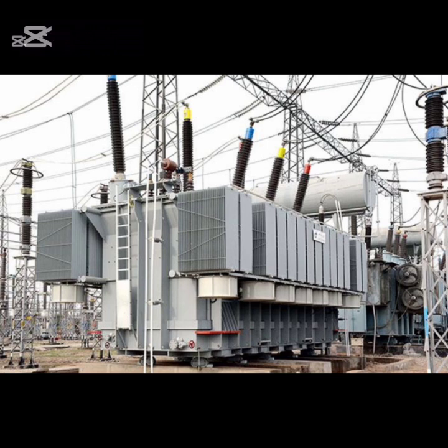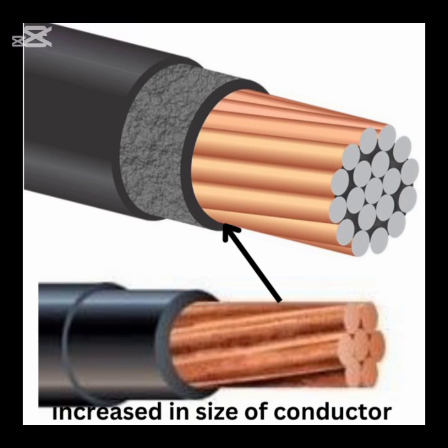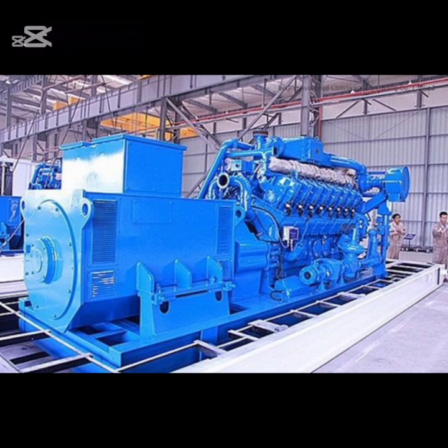4. Larger equipment. Electrical systems with a low power factor may require larger transformers, conductor sizes and generators to handle the increased apparent power, which translates to higher initial costs and increased maintenance. This is because power factor is inversely proportional to the apparent power measured in volt-amperes. As the current increases due to poor power factor, the system will become larger to possess the required current carrying capacity for the design, thereby making the size of the equipment larger.